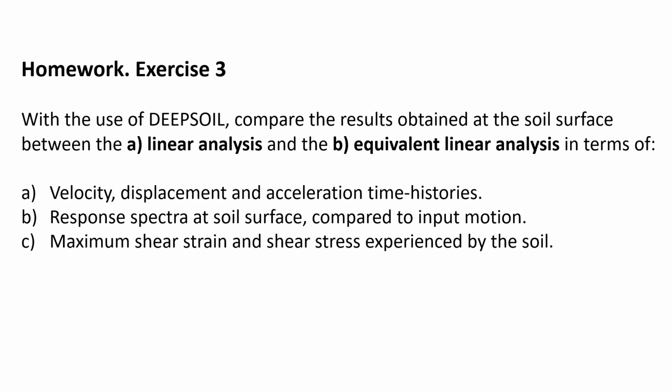The purpose of exercise 3 will be to use DEEPSOIL and, by undertaking the linear and equivalent linear analysis, based on the information collected before from each one of the two exercises. That's why I recommend you save the profiles and the results and then export them into Excel. Calculate velocity, displacement, and acceleration time histories for each one of the analyses, response spectra at the soil surface compared to the input motion, and then calculate maximum shear strain experienced by the soil, and see the difference between linear analysis and equivalent linear analysis.